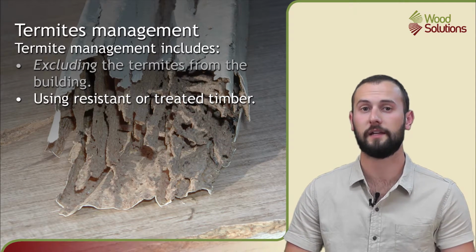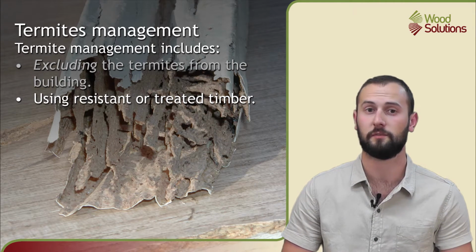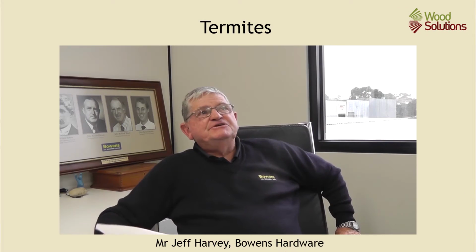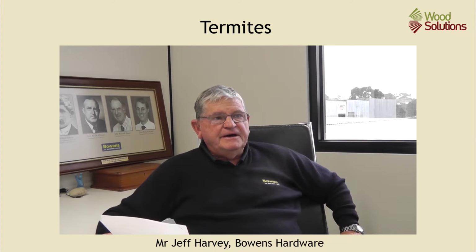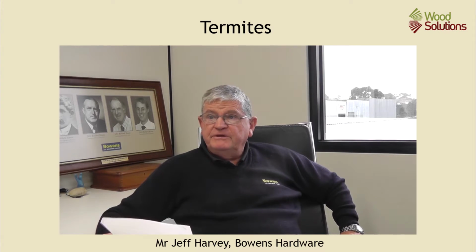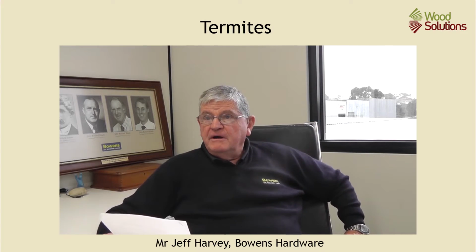Recommend at least H2 treatment for internal structural material and H3 treatments for external applications away from the ground. You must consider termites in the context particularly of a subfloor situation. Ventilation is very important there. Perfect havens for a termite nest is a poorly ventilated subfloor.